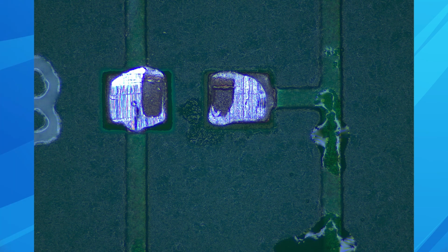The first thing you can do is to focus on those failing components. Shear them off and take a look. See if you can see any residues underneath them. This can significantly help you to adjust your cleaning process to make sure that you have success.